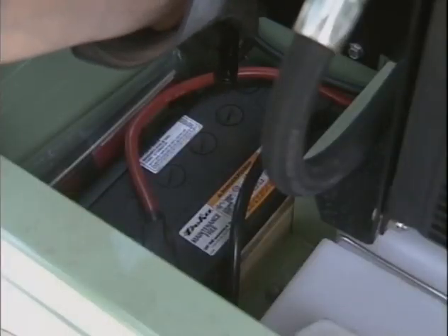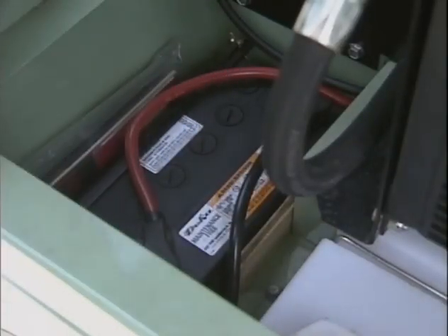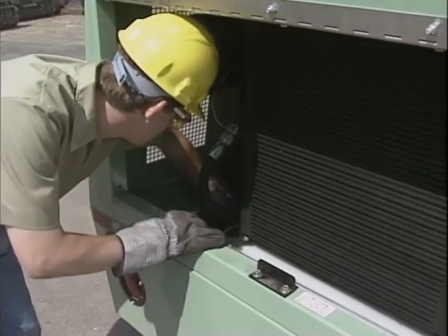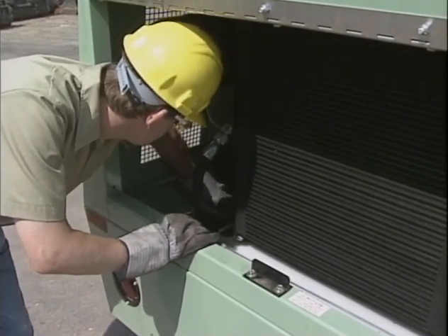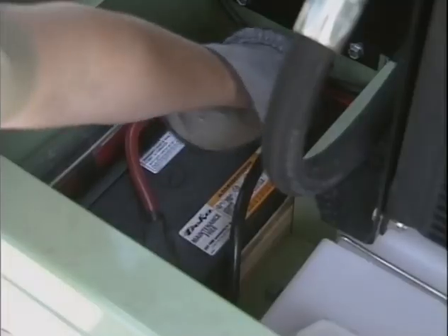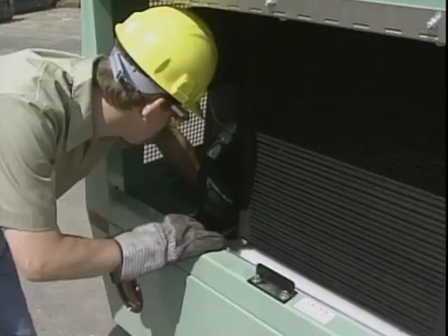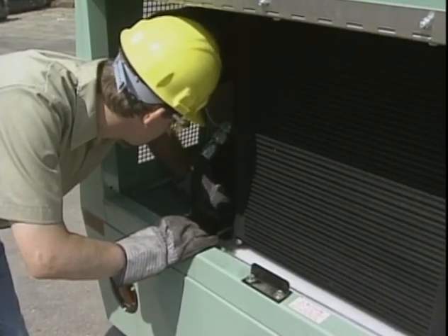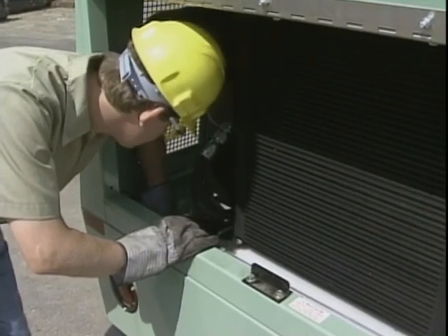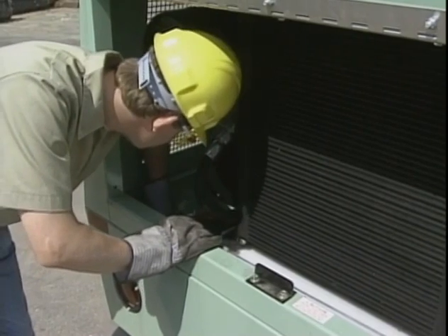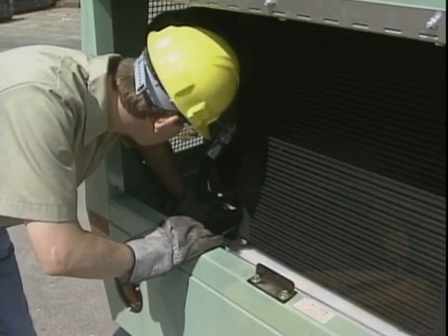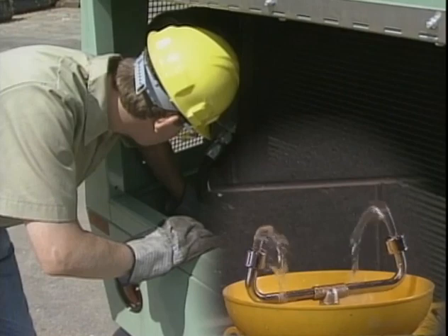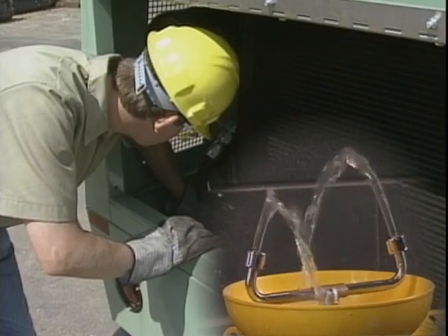Use a flashlight to check battery electrolyte level. Always check with the engine stopped. Battery electrolyte is poisonous. It is strong enough to burn skin, eat holes in clothing, and cause blindness if splashed into eyes. Always wear eye and face protection. Flush any contacted area with water immediately.